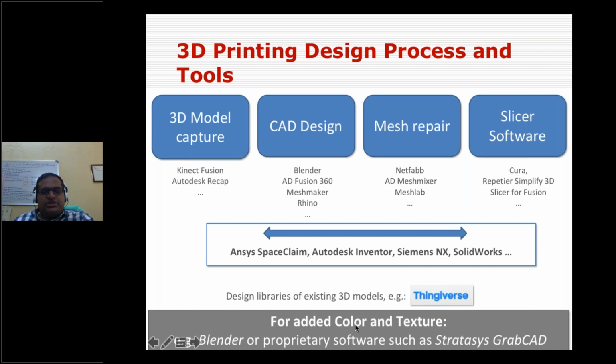So you are going to add some colors. As we understood from the second session, STL file doesn't contain color, STL file doesn't contain any texture, STL file doesn't contain any material, STL doesn't contain any volume. So we need to enhance. Why? Because your printer is able to print in color, in different textures, lattice structures.